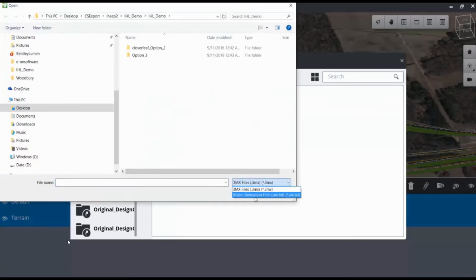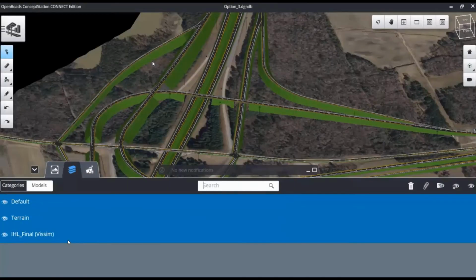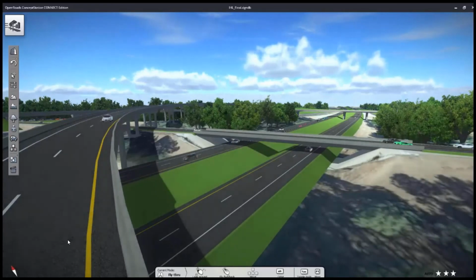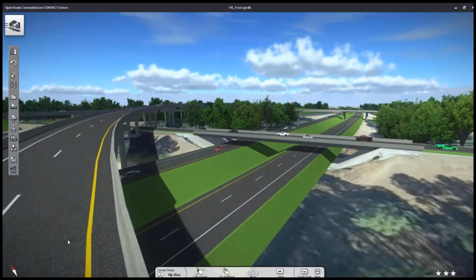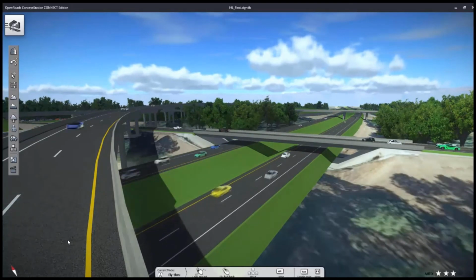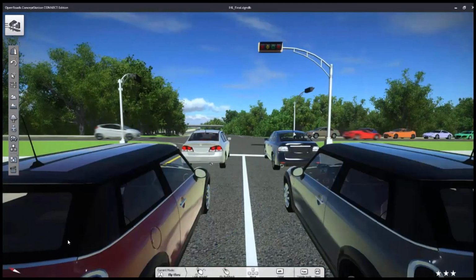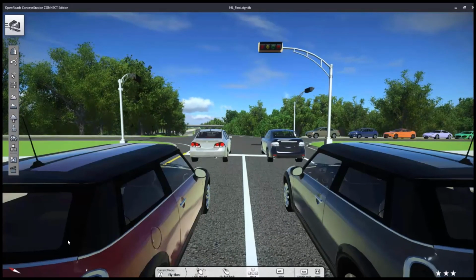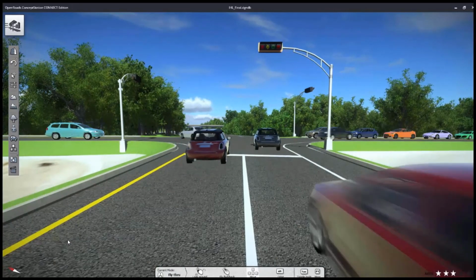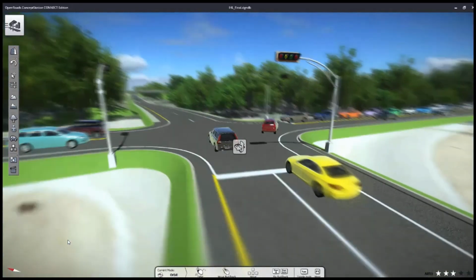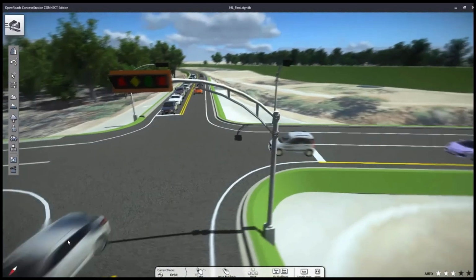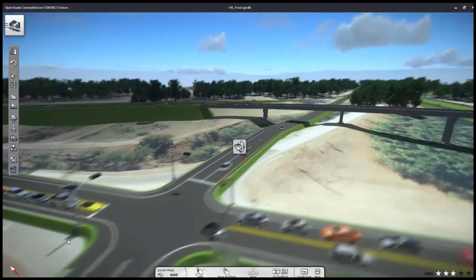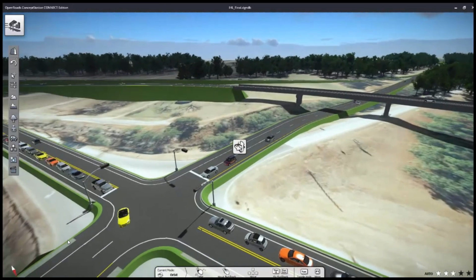So now we can bring that in, and we can go to visualize, so we can actually see that traffic. And if you have staging at stoplights and timings, you can check that too. That's something that VISSIM does quite nicely. So you can see if your turning patterns and the timing work for the amount of traffic that you expect on the various roads.